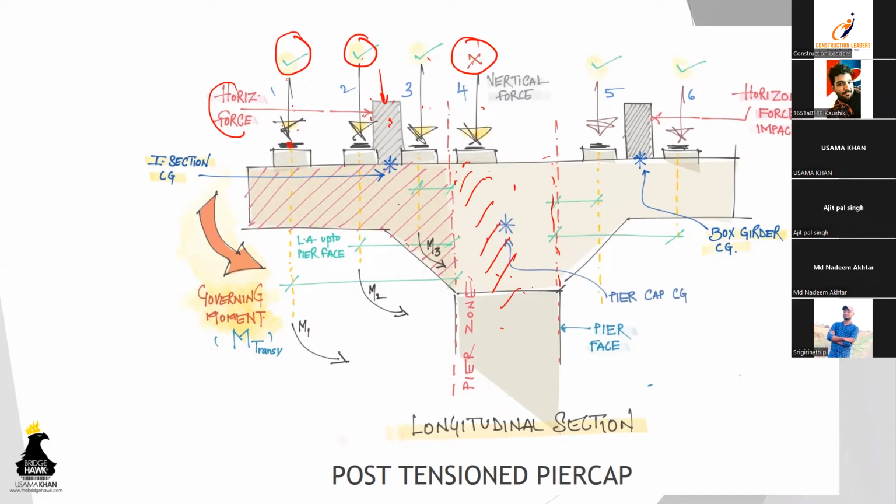So we have these point loads which are directly incident upon the bearings. We have a force acting upon them, with a subsequent lever arm. We'll have different lever arms. The lever arm is taken with the reference point of the pier face. This is the lever arm for the point load P3. This is P2, and this is P1.